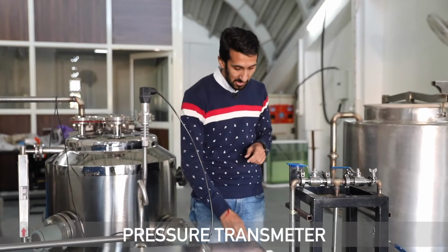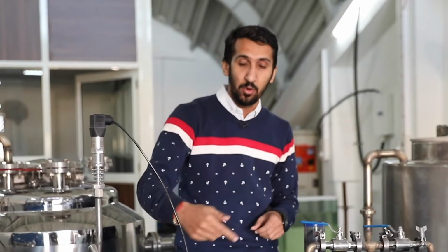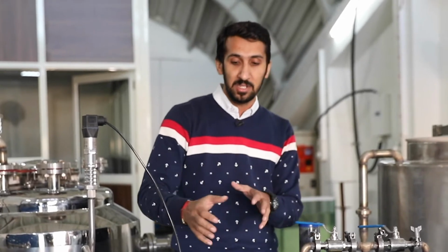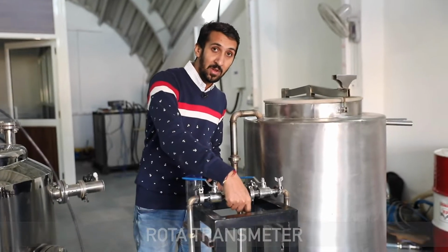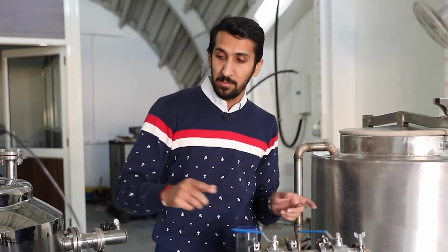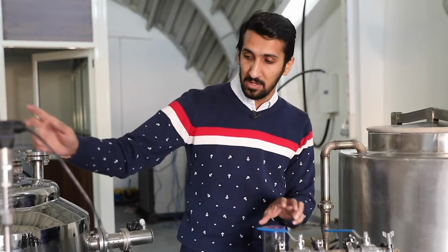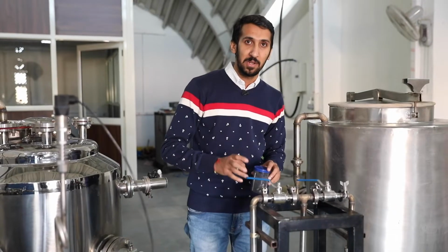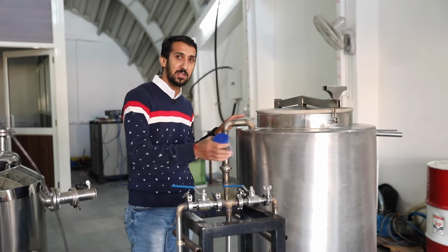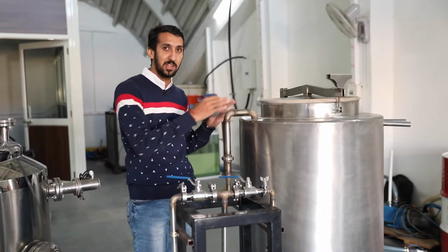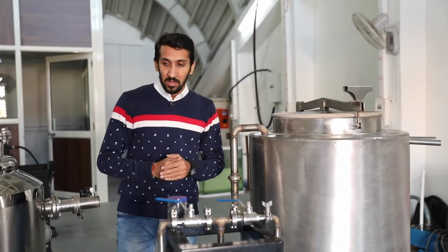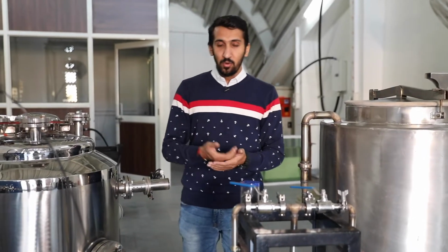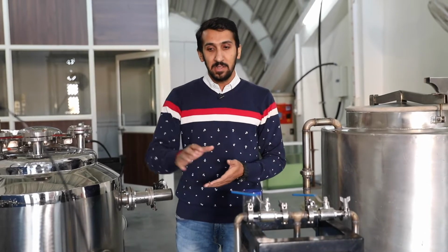And these are some measuring instruments. This is a pressure transmitter. This is also a pressure transmitter. We are going to measure the pressure loss due to these pipings and these bends. And this is the rotameter to calculate the mass flow rate during the entire circuit. After the charging process, all of the HTF will be stored in this second stainless steel container. So we are going to store the latent heat in these heat exchangers.